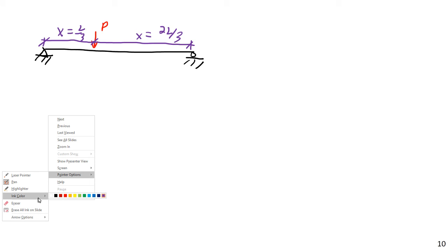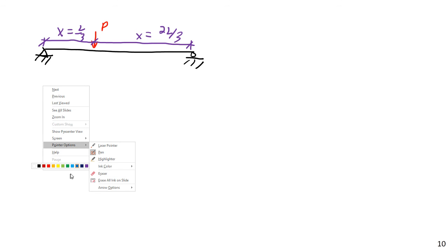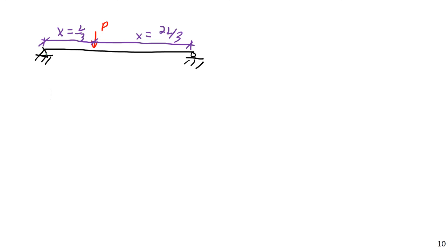What do we know? Well, let's say I had two equations here. First, let's look at the deflected shape. It would not be symmetric. The lowest point in the beam would be directly underneath the point load. It's going to be something kind of like this. This is kind of exaggerated, sort of like a swoosh, like that.